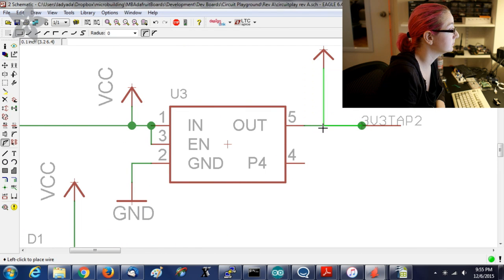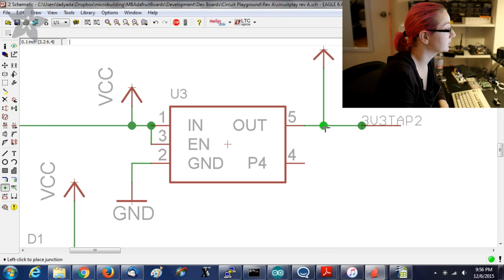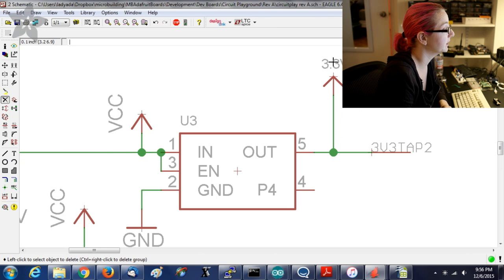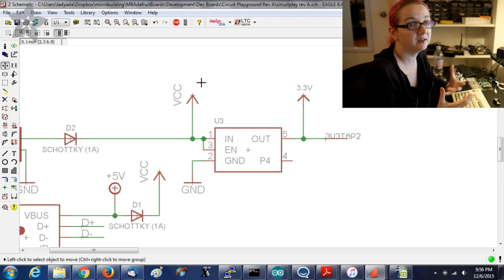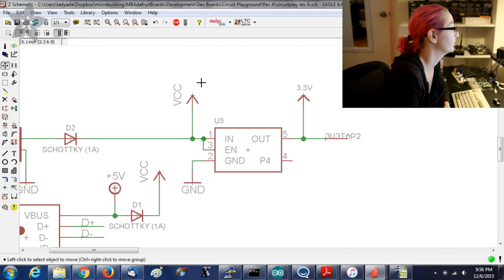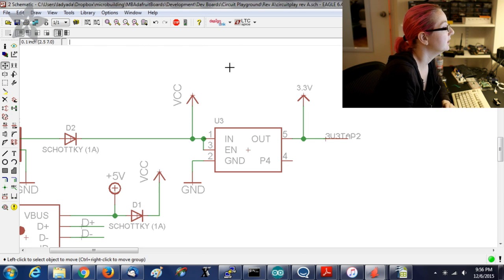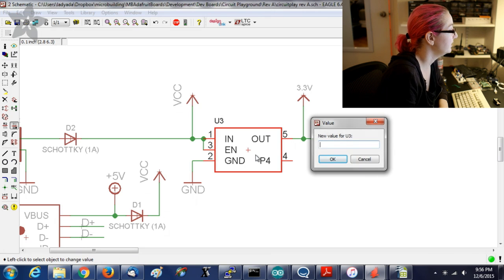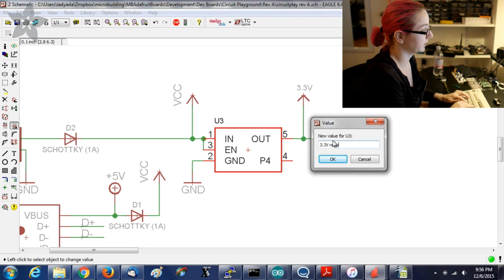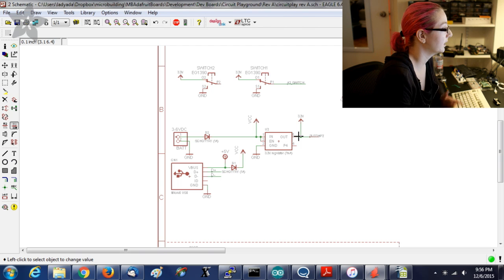Also to VCC, and then VCC basically just goes into this regulator, and this is a 3.3 volt regulator. Make this super clear, and then there's this tap. Talk about that a little bit later, but so this is 3.3 volt, and VCC basically can range from 3.5 to 6 volts. So it's a non-stable voltage. It's V high, but what we really want is to have everything run off of 3.3 volts. And so this is the 3.3 volt regulator, and then question mark milliamp, because we haven't set our power budget. Well, I have in my head.